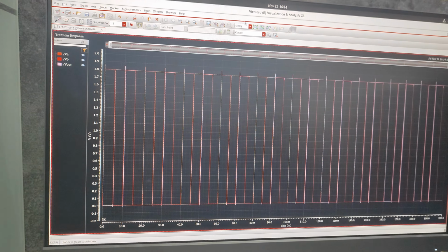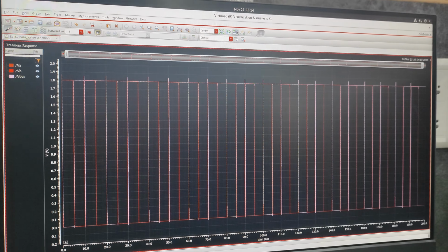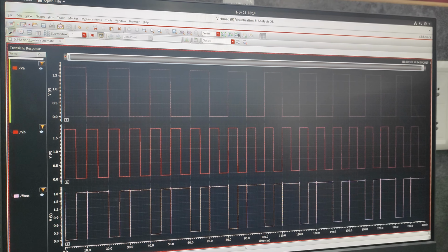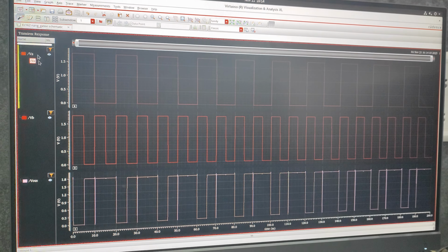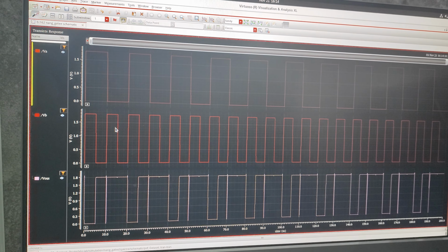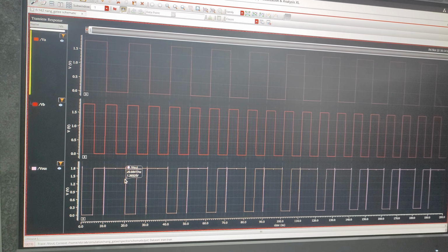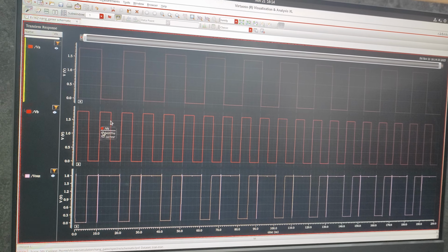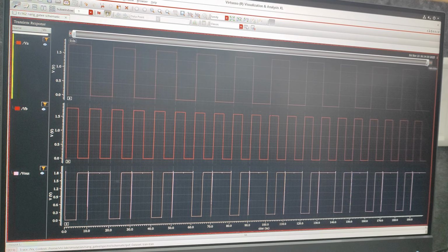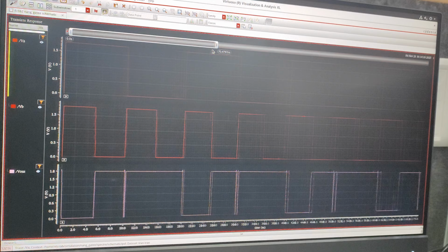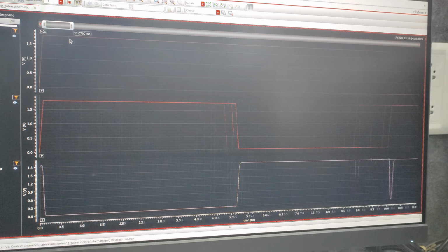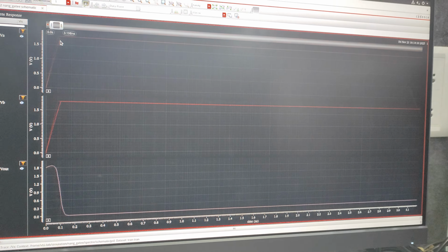After making this waveform maximize, then you have to click on split current strip. Just click on that. So you'll be getting our input VA, VB and V out. With the waveforms, you are supposed to verify whether the output is correct first. Okay, if it is correct, then you can proceed. So this is correct. Then you have to minimize this for seeing the rise time, fall time and propagation delay